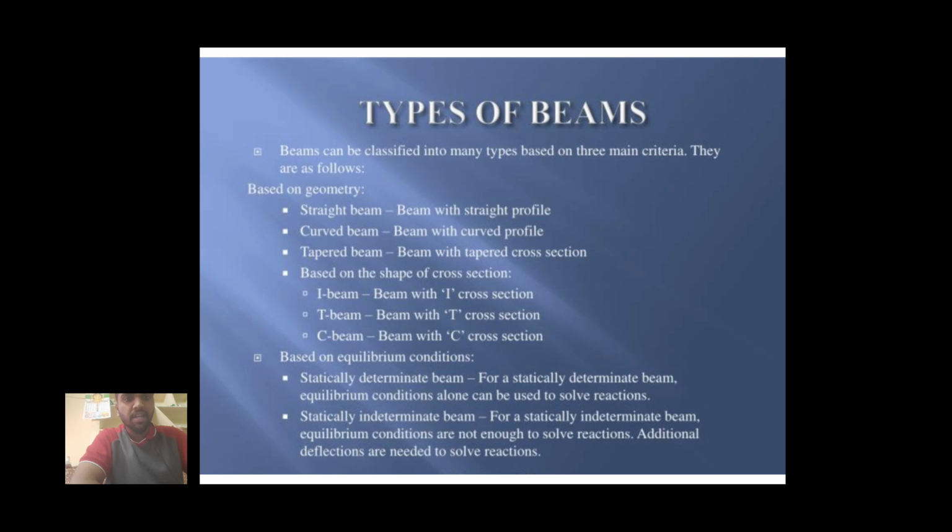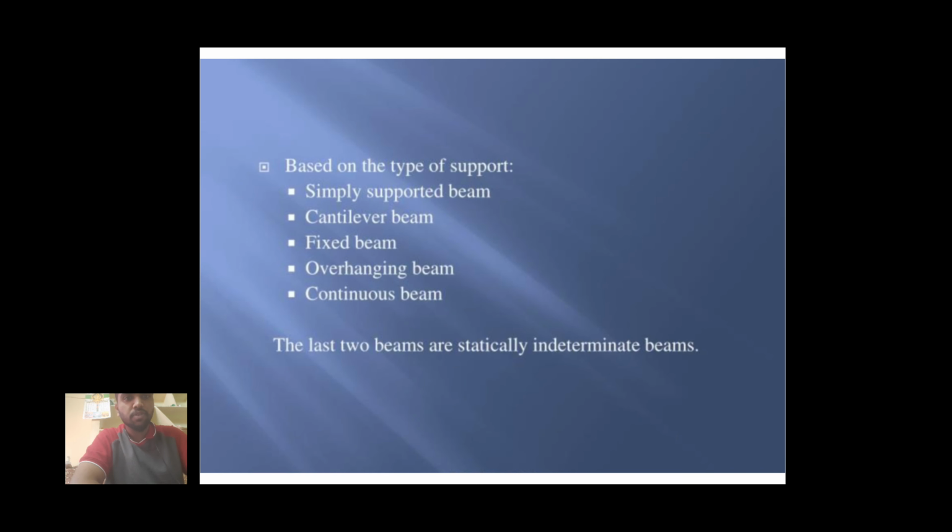Based on equilibrium condition, statically determinate beams: for a statically determinate beam, equilibrium conditions alone can be used to solve reactions. Statically indeterminate beams: for a statically indeterminate beam, equilibrium conditions are not enough to solve reactions. Additional deflection equations are needed to solve reactions. Based on the types of support: simply supported beam, cantilever beam, fixed beam, overhanging beam, and continuous beam. The last two beams are statically indeterminate beams.